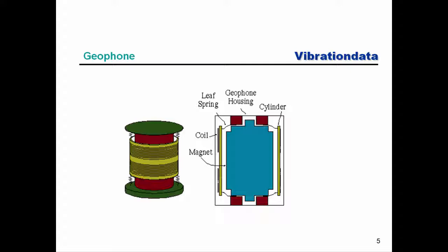And I think the idea there is that the magnet itself would be vibrating vertically, and the coil itself is mounted on very compliant springs, so that would tend to remain stationary, and then the relative motion between the coil and the magnet would cause a current or voltage that is proportional to velocity. So that's one way for directly measuring velocity.